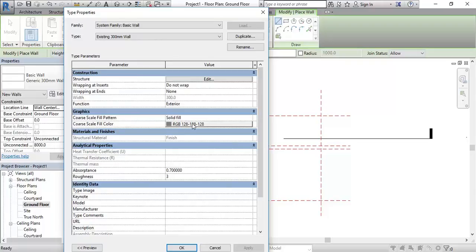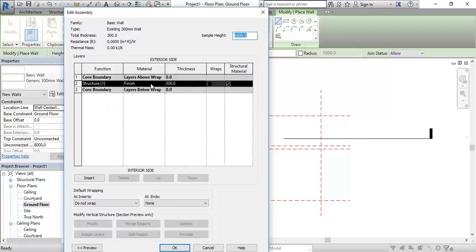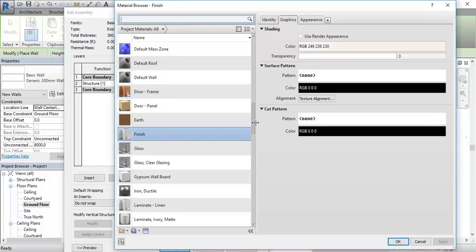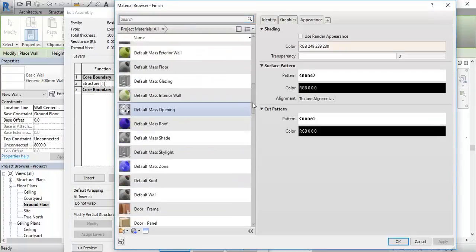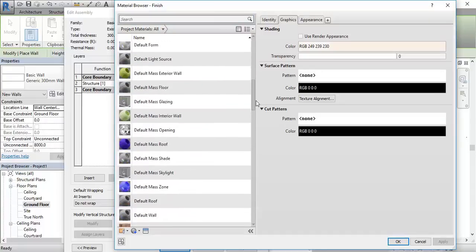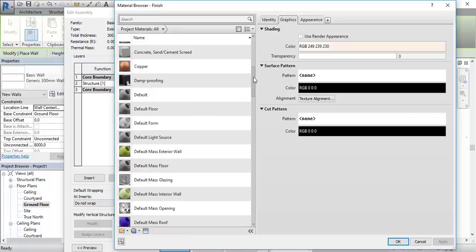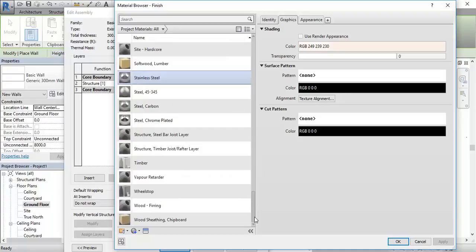And so then, how would you think you'd get the black fill that I was talking about? Using material? Well, if you're thinking materials, you're thinking the right way. We've briefly looked at it, but you maybe haven't gone through all of these. You can see there we've got all these different materials we can assign to the wall. So that is often the first thing you do if you want to change the appearance of your wall. But I'm not going to do that. I'm going to cancel this.